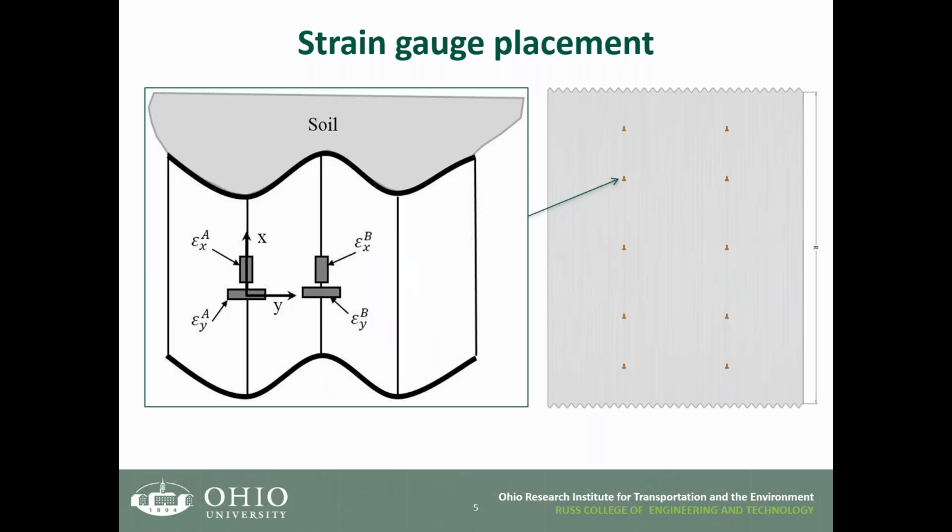So in that case, the material that applies the load, the same material also carries part of it. That's the thing. From undergraduate, in the first course we teach in structures, we are always taught that the larger the moment of inertia, the more load you can carry. But in the pipe, that is not the case. There are cases where you will have a larger moment of inertia and the pipe will be very weak, because in corrugated pipe, the shape is very important.